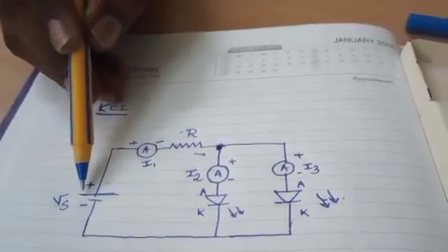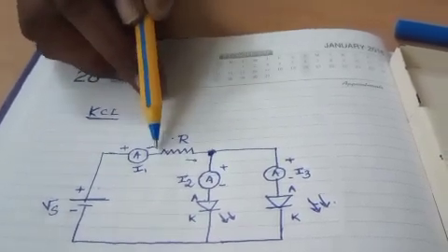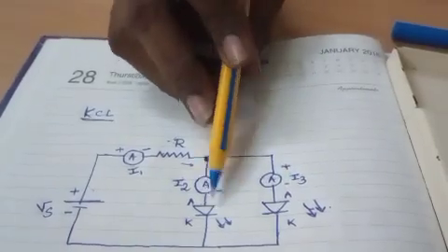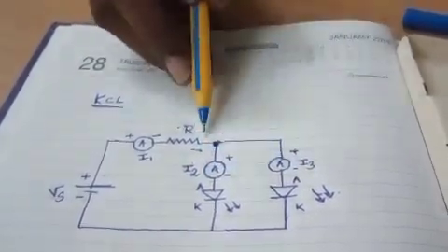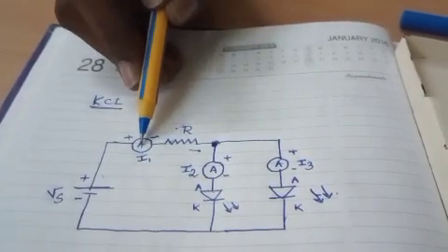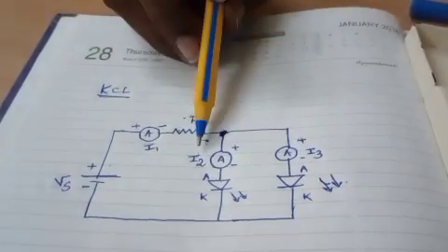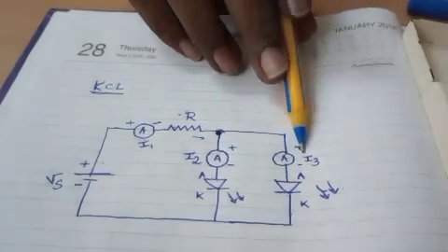We have connected RPS plus to ammeter plus, ammeter negative to the resistor one end, and then these two LEDs we have connected in parallel, and the parallel side, that is the common anode side, is connected with the resistor's other end. Okay, actually I put here only one ammeter, so that can measure I1. Then if you want to measure I2, I3, you can replace this meter here and there, so that we can get I2 as well as I3.